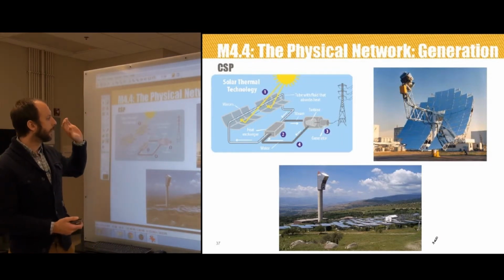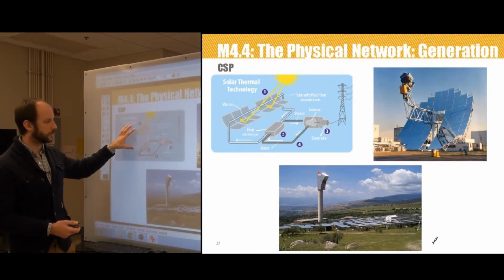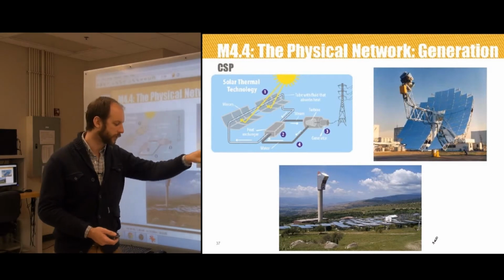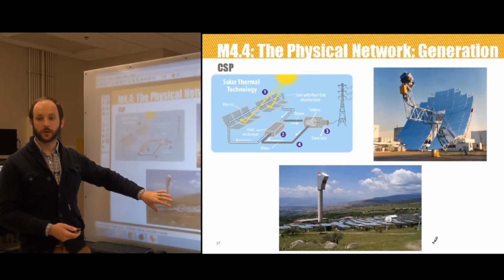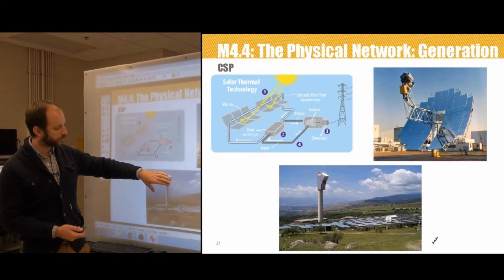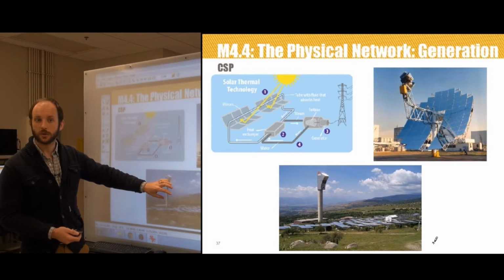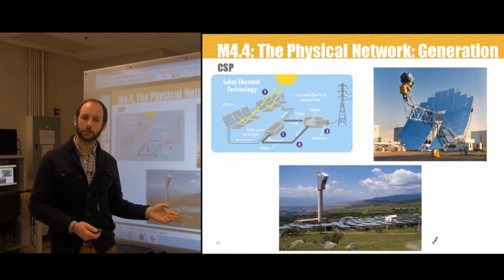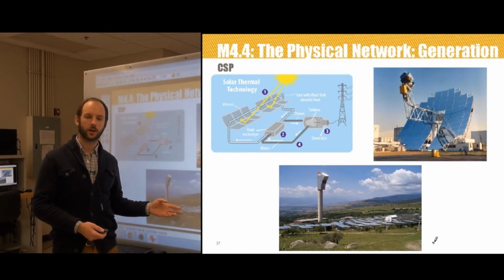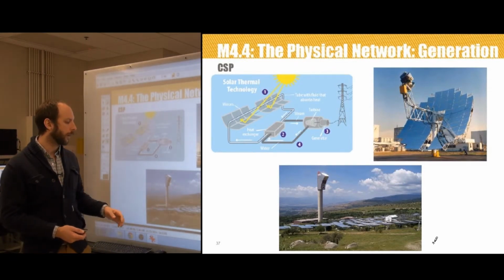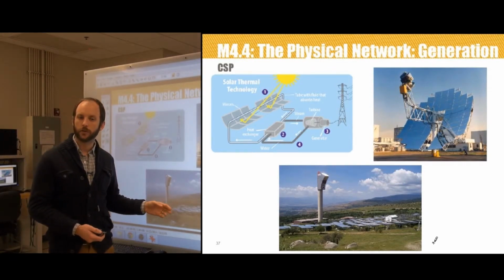So these are actually used in utility scale. That's its major claim to fame. This guy holds the record, 31.25% solar efficiency. This guy, however, for a number of hours after the sun has stopped shining, there still is stored heat inside the thermal mass inside of this power tower, which you can still use to boil water. So this guy can produce power even when the sun isn't shining. It can help flatten out some of the effects of intermittency of the solar resource.